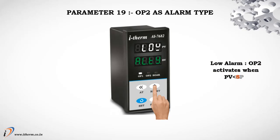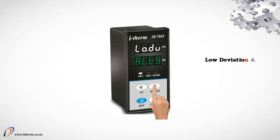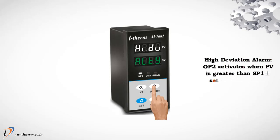Low alarm, output 2 activates when process value is less than setpoint 2. High alarm, output 2 activates when process value is greater than setpoint 2. Low deviation alarm, output 2 activates when process value is less than setpoint 1 plus minus set deviation value. High deviation alarm, output 2 activates when process value is greater than setpoint 1 plus minus set deviation value.